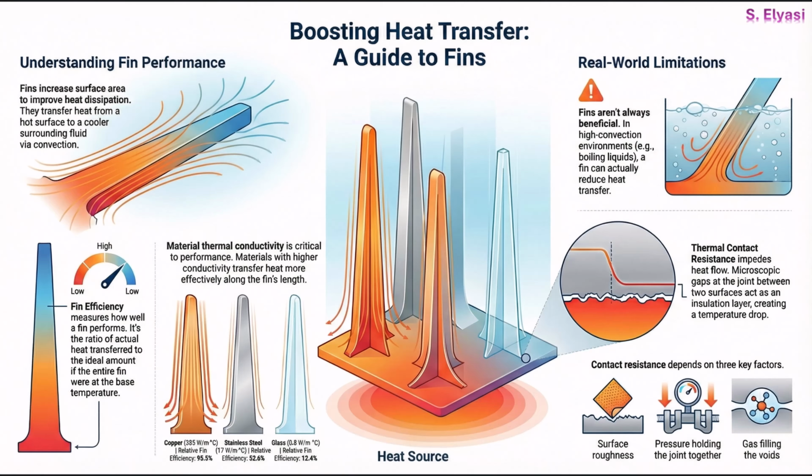Heat transfer fins. Fins are that crucial engineering trick, like the vanes on your computer's CPU cooler, that are all about getting heat away from a surface and into the air. But how well they work isn't always so simple. First, it's all about maximizing surface area. This gives heat more space to escape through convection.